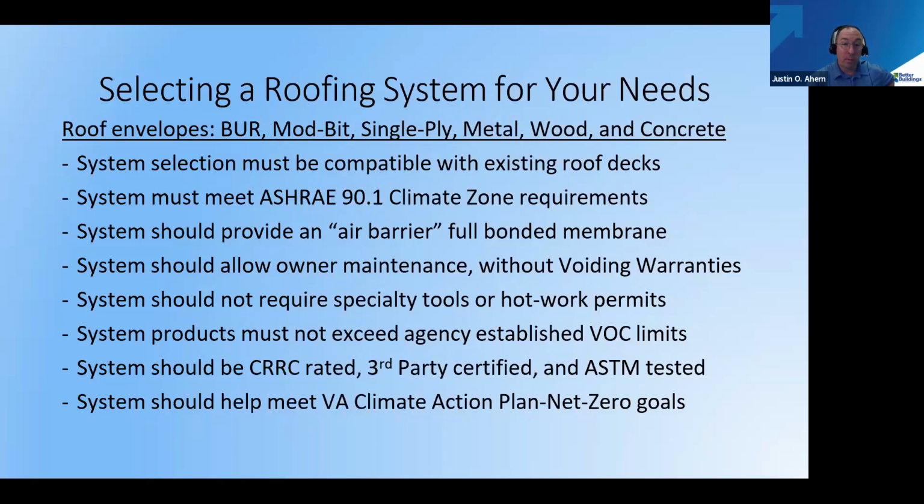Verify systems can be applied to your roof with net zero benefits. An example, if you have a modified bitumen roof cap sheet, you can install a single ply membrane that's not a building code compliant system. With an overlay, you don't have to meet a new installation requirement. There's a whole bunch of inspection requirements and everything else that just don't apply because you're adding it to the existing roof system that's already grandfathered in.